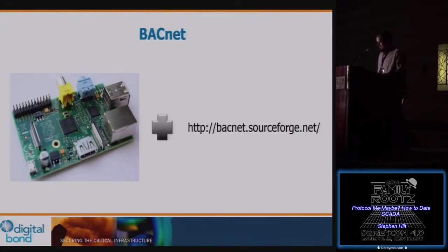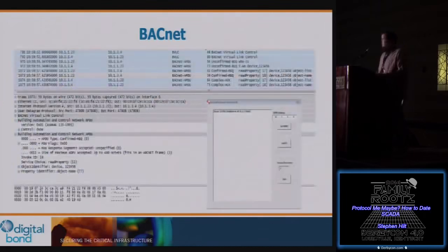formatted correctly. You can also use, on the bottom right-hand corner, a screenshot of a BACnet browser. BACnet is tree-based, most of the browsers pull the objects into tree format. So you can see in the packet capture there, read properties, like 17 and 18, object name and object list. So that shows the information based off the table that we saw in the standard, and then using Wireshark. Once again, people are very awesome and write really well dissectors already for you most of the time. So it helps you doing a lot of this work about which fields are what and then how to also interpret them.